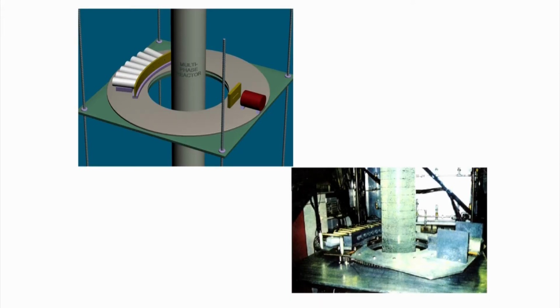Now, if you want pixel wise information, a detailed distribution of the volume fraction pixel by pixel, we need to acquire the data in a different way. So how can we acquire the data? We can have two kinds of projection. In one case we can use one source and several detectors, and in the other case we can use several sources and several detectors. So two different projections are used.